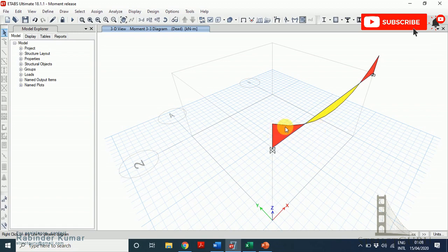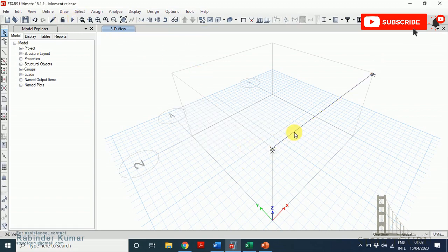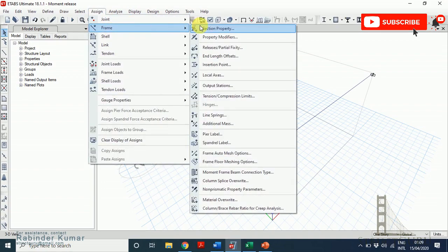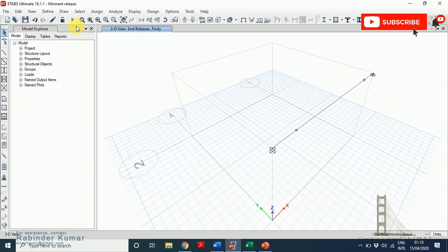So let me make it a pin connection. How will we do it? First unlock the model. Select the beam. Go to the assign menu. From frame section we have to select release or partial fixity. Select start point, select end point. I'm not putting any value over there. 0 means by default we are making it a pin section. We are reducing the stiffness to 0. So click OK. Run the analysis.